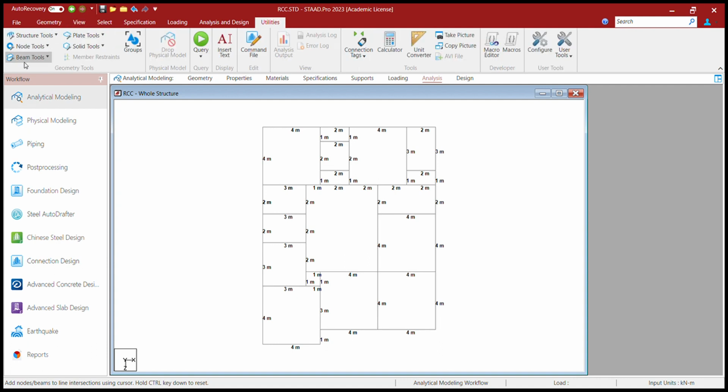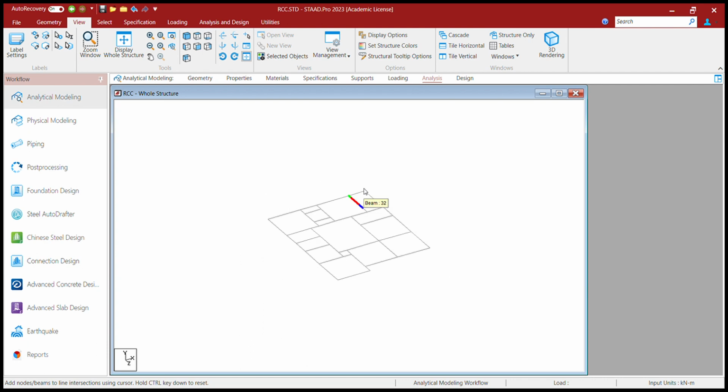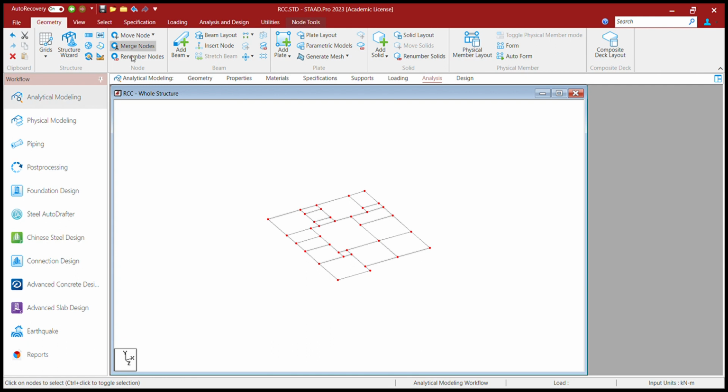So now we'll just remove the dimensions. We'll see it in a grid isometric view. Now we'll create the column. First we'll create the bottom story, and then we'll repeat it in upward direction. So for that, first select all nodes of this total structure, and we'll use the translation repeat command in downward direction, that is in y direction, with a column height of 3 meter, sorry, in minus, we need to put it minus 3 meters, so that we will have the column in downward direction with a link step.